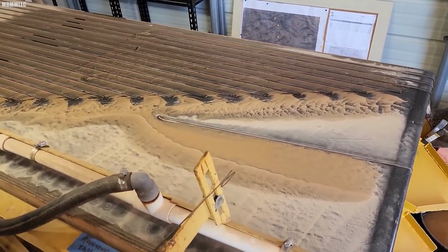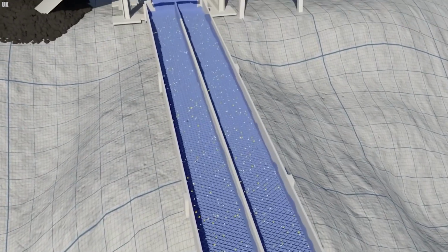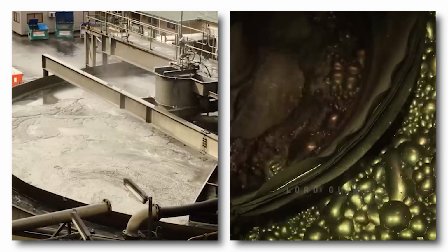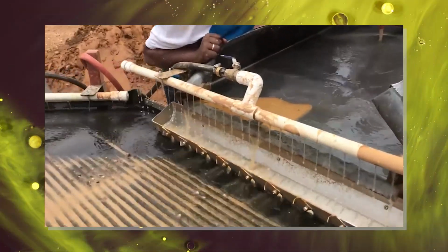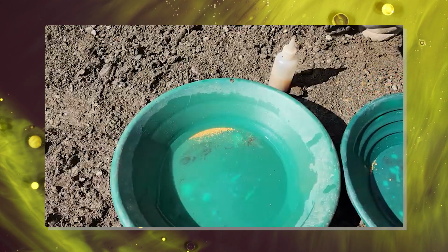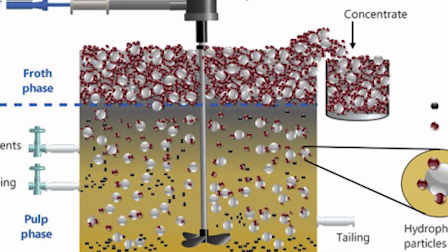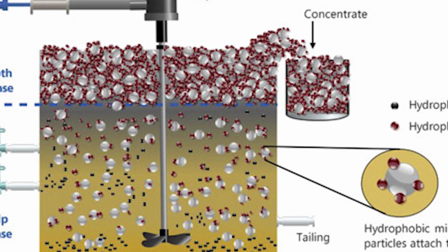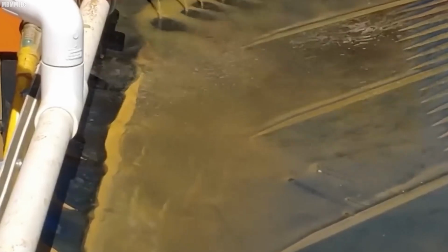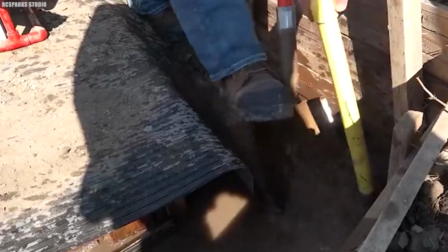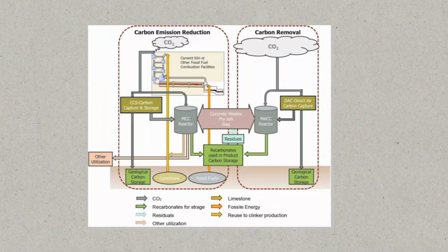It's about increasing surface area. When the ore is finely ground, a greater surface area allows chemicals used in subsequent extraction processes, like cyanidation, to interact more effectively with gold particles. Fine particles ensure that gold can be liberated from other minerals more easily during concentration methods such as gravity separation or flotation. After that, optimal leaching is employed because smaller particles improve leaching efficiency by allowing better penetration of leaching agents.